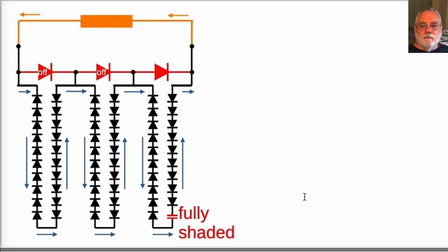Now, suppose you have multiple solar panels connected in series to a string inverter with no microinverters or DC power optimizers. If an entire solar panel is completely shaded, or all three strings have zero current, the active load of the string inverter should forward bias all three bypass diodes, and current should flow through the multiple solar panel system, even without microinverters and DC power optimizers.